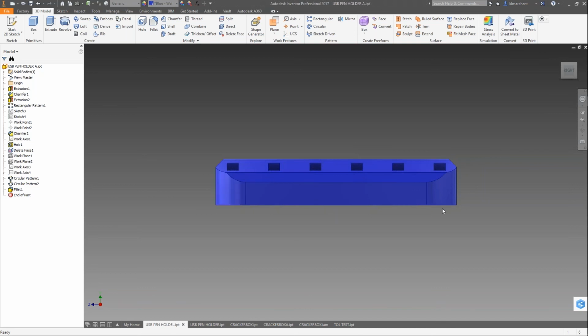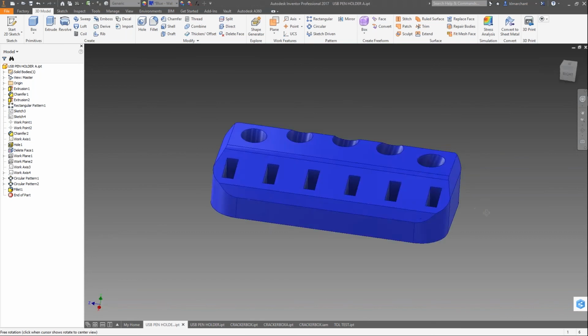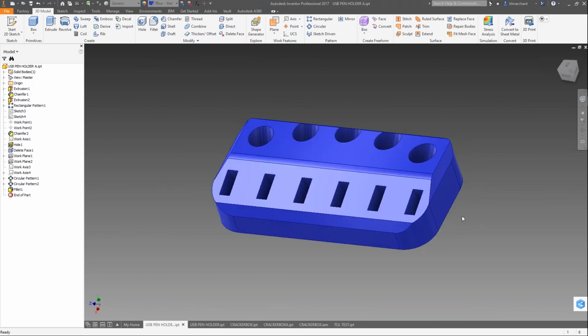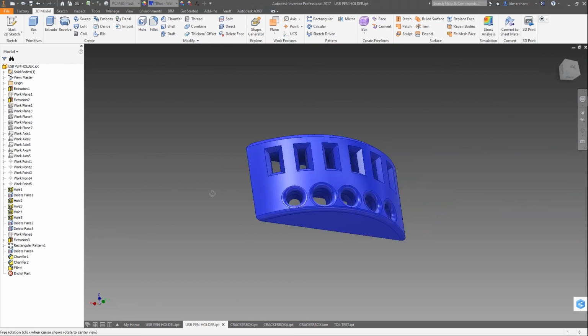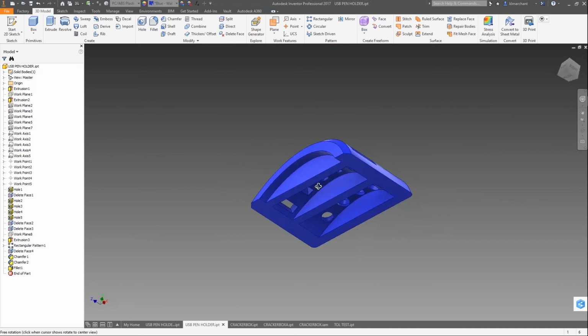What I learned from that, in my earlier days of FDM printing, was that this large block, roughly 4x2 and about an inch tall, maybe 3/4, was that much material on that small of a footbed, and it warped. If I hold down one side, the other side is a good 1/8 of an inch off my desk. As soon as it printed and I noticed how badly it was warped, I realized I needed to redesign this part.